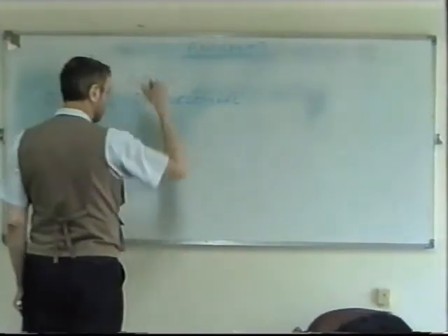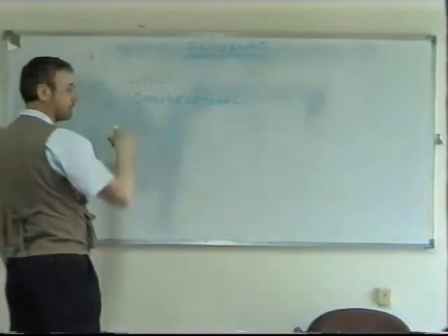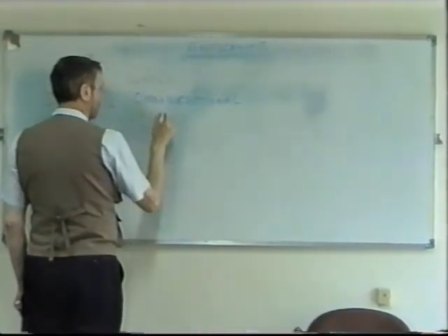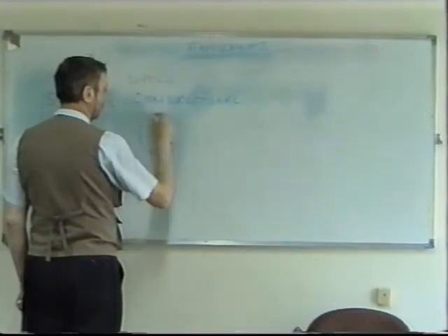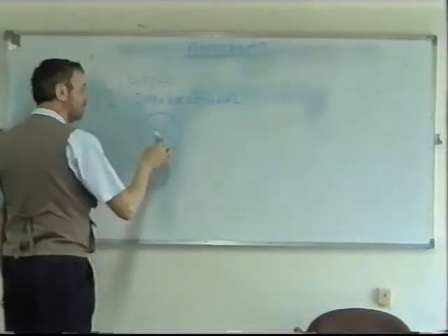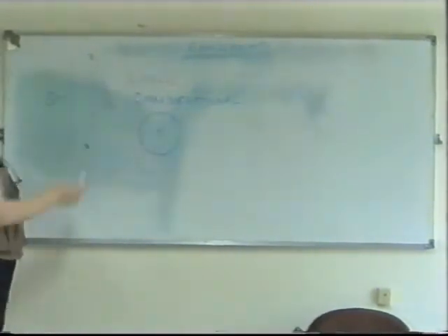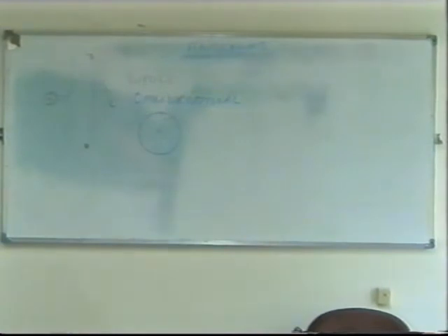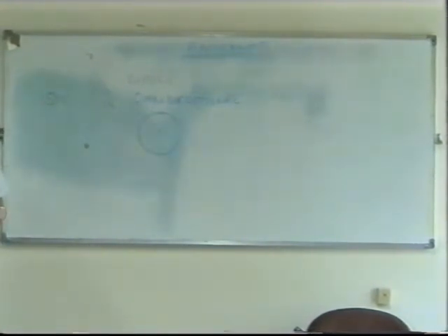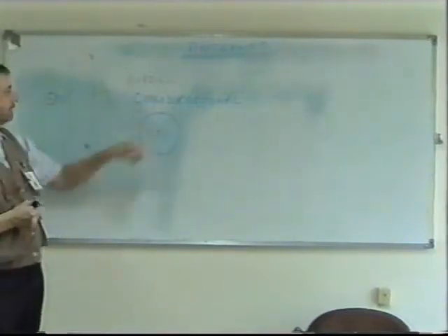The polar diagram, looking at it from the top of the dipole, should be perfectly circular, symmetrical like that. This is the polar diagram. So it doesn't matter which direction you are in from the antenna, you should get the same signal strength wherever you are. A lot of people get a little bit confused about what this diagram represents.